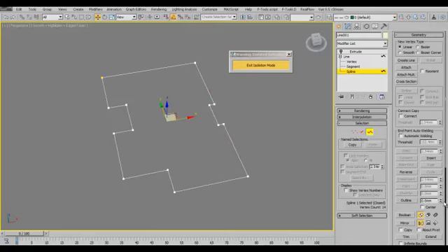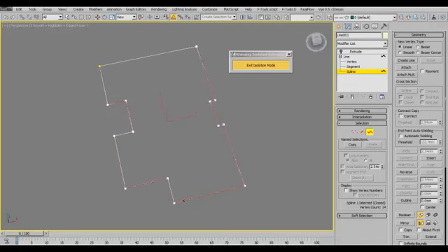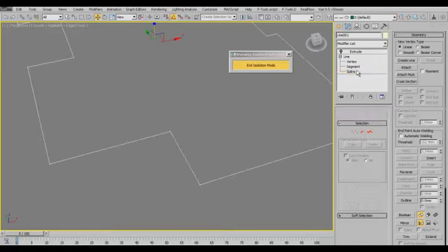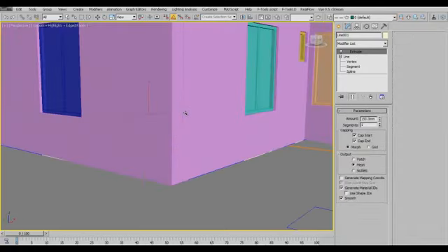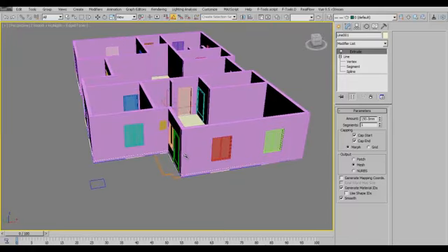So now I'm going to use a -10. Now that I've used a -10, what it does is shift and create another one inside. So I'm going to delete the initial one and leave the current one, so that when it extrudes, it doesn't come up and show up on the surface of this wall here, which is actually very good.